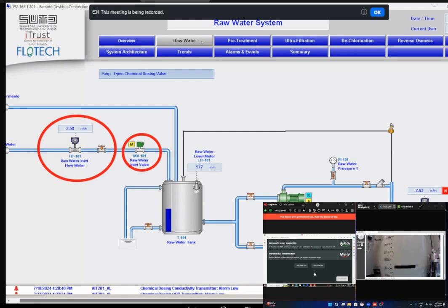In this particular case, if the water level rises beyond a certain point, as you can see on the screen, there's a lot of turbulence on the CCTV screen in the water level of the tank. Beyond a point, if this is left unchecked, the water level will rise to all these different set points that you see on the CCTV screen. For example, the 1200 liter set point, the 1600 liter set point, and beyond a point, the water will overflow. So we can already see that the water level is higher than where we started. And if left unchecked, this water level will go beyond 600 millimeters in a few seconds to all the rest of the values, which will basically result in flooding.